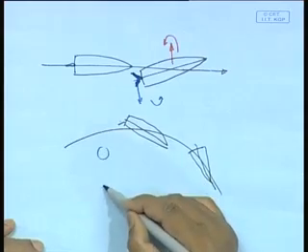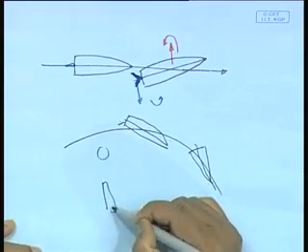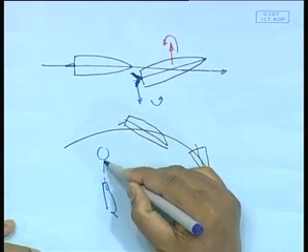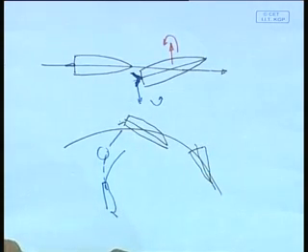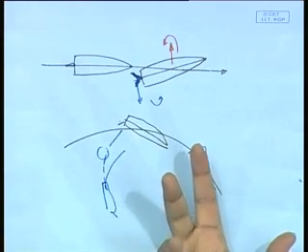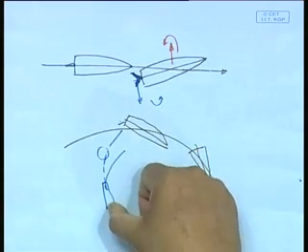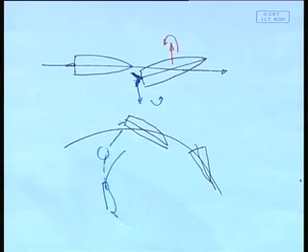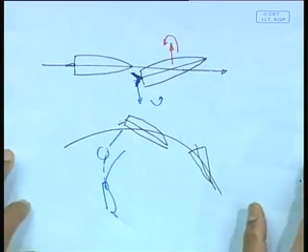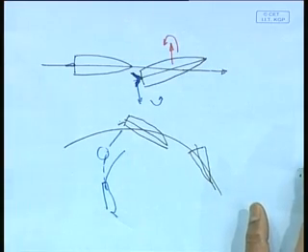Even though you saw the object here and you were coming here and you gave a rudder, you actually went more like that. You didn't go straight like this. The ship didn't respond, because if it was a car and I gave a large rudder, it would have turned immediately, but it did not. All this tells me that understanding maneuvering is a little more complex because it is nothing but an interplay of forces.